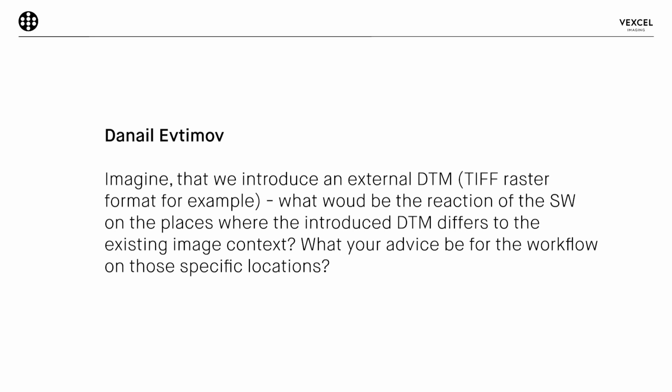If the heights of the external DTM are wrong or are far off by some reason, the software will not give an error, but the software will do the rectification of the images accordingly to that height, and will also do the orthomosaic accordingly. So this is in the responsibility of the user to get the height right, to import data which matches the images, and then you get a good product.